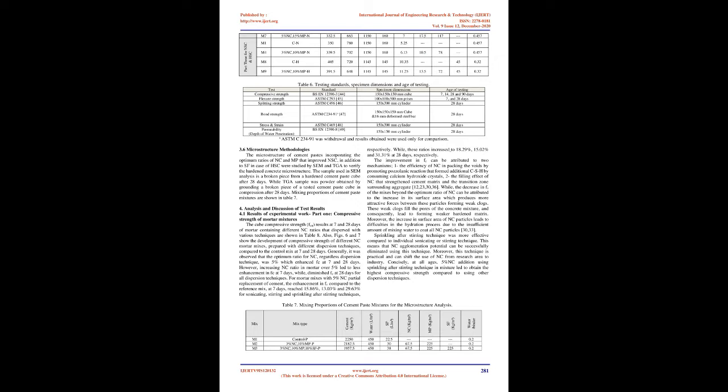2. The mean particle size distribution of MP was 7.25 µm as shown in Fig. 3. TEM micrograph of MP shows spherical shaped particles as presented in Fig. 4. XRD analysis presented in Fig. 5 shows calcite composition and crystalline lattice of MP particles. Silica fume, SF, is a condensed fine powder which has pozzolanic activity and is a byproduct of the manufacture of silicon or ferrosilicon alloy.